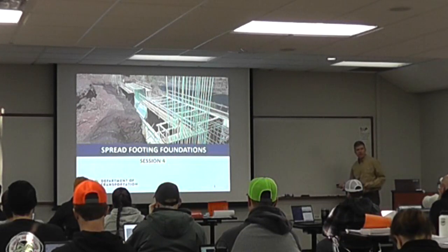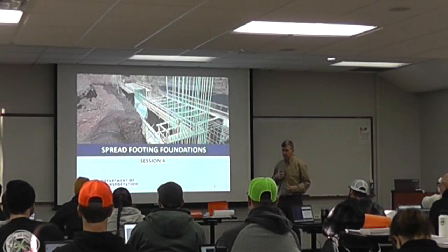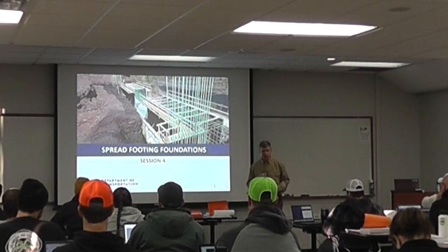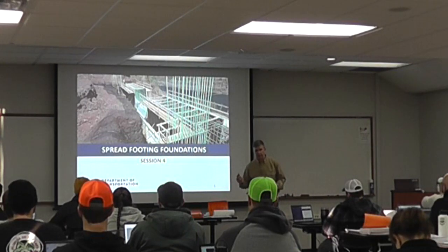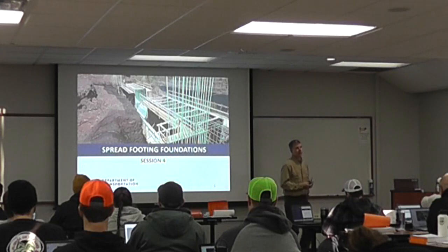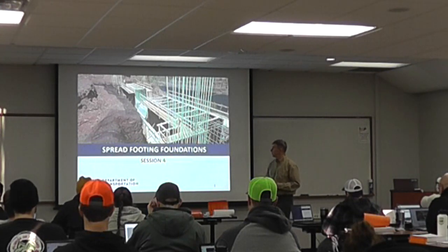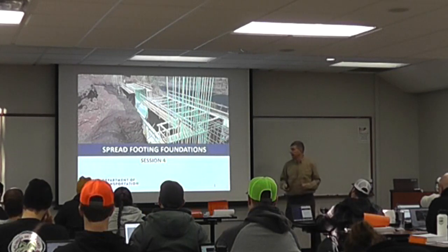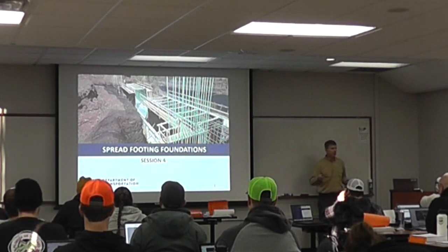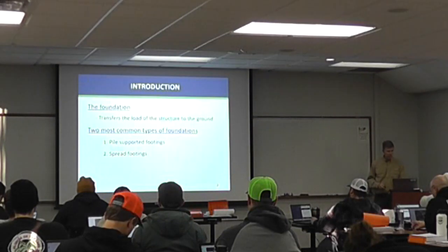I would say on the foundation recommendations that I wrote when I was the Metro Region bridge engineer, I don't know, less than 10% for sure, probably only maybe 5% of bridges, at least in the Metro, utilize spread footings, but they do get used. And also sometimes you'll see them on retaining walls, especially if they're not very tall. So we can get to see them.